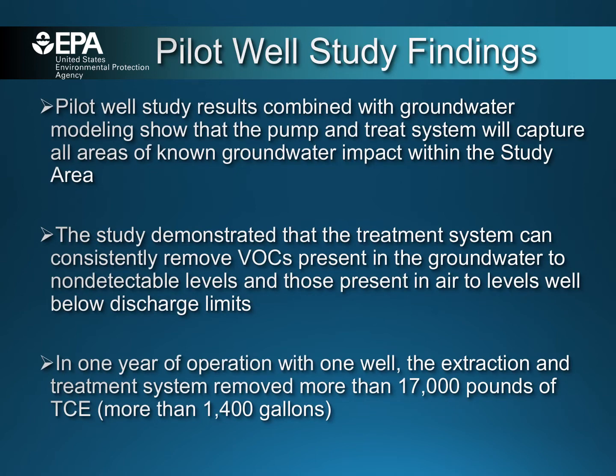The groundwater hydraulic conductivity, or slope, in the area is reasonably flat. We wanted to evaluate the groundwater flow and contaminant concentrations and measure the change when a pump was applied. The pilot well study, Extraction Well 1, results combined with groundwater modeling show that expanding the system could capture all areas of known groundwater impacted within the study area.